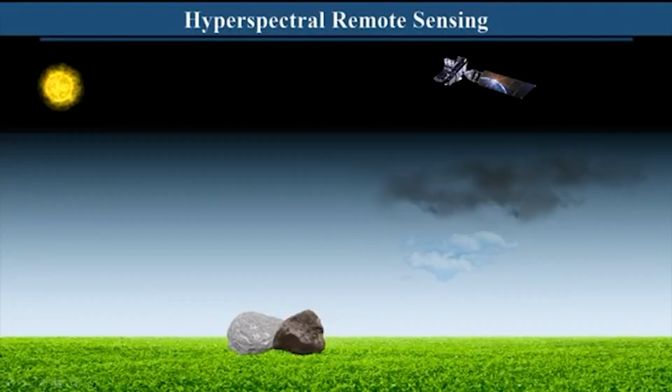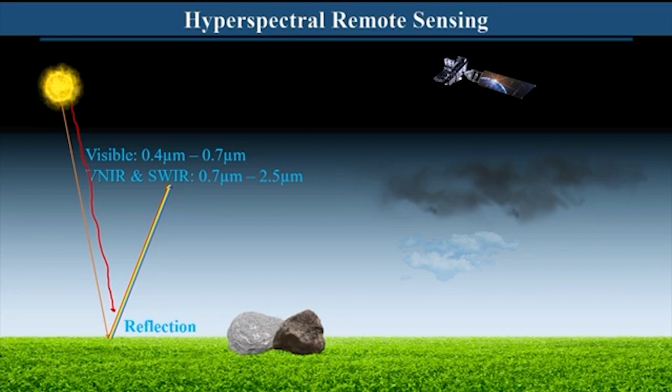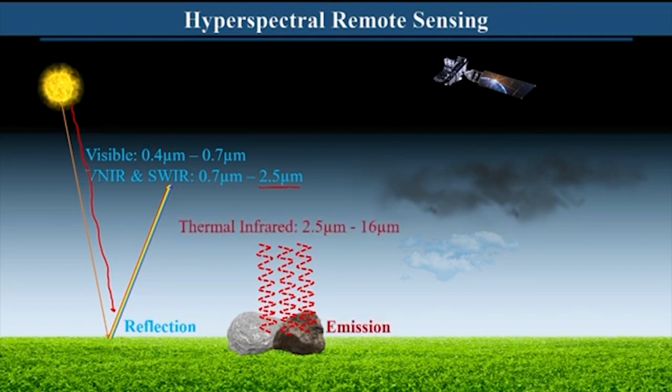show you, because this is the fundamental of remote sensing, where in case of passive remote sensing we are using the sun as our source. The sun is illuminating our surface, right, and it is getting reflected, and the reflected energy we capture between 0.4 to 2.5 micrometer wavelength range, whereas in emitted energy we use 2.5 or 3 micrometer to 16 micrometer wavelength range, and there we capture the emitted energy. So, the information will be volumetric.